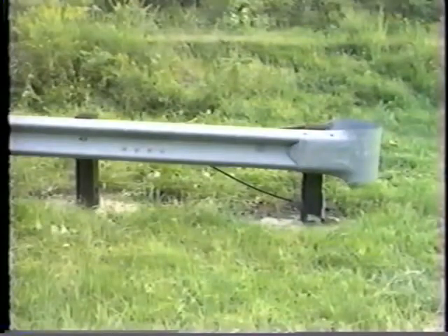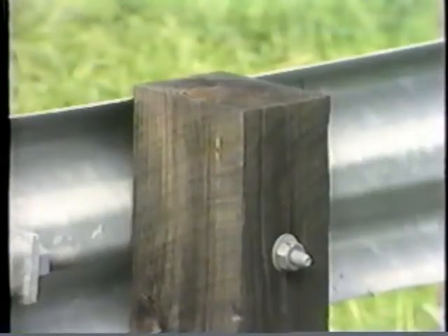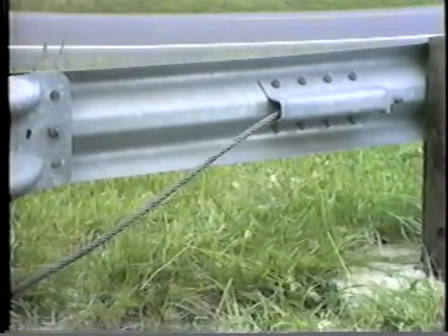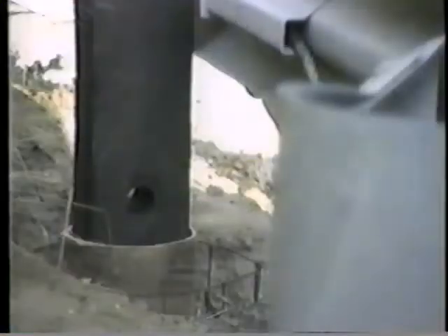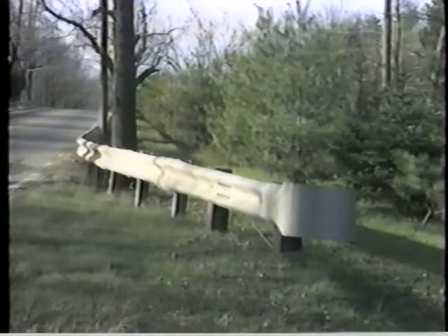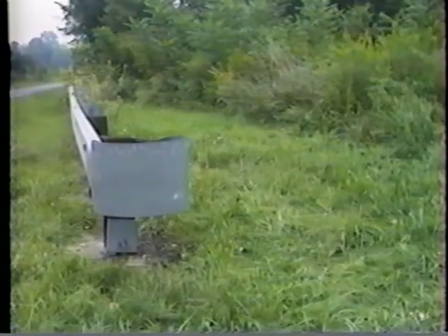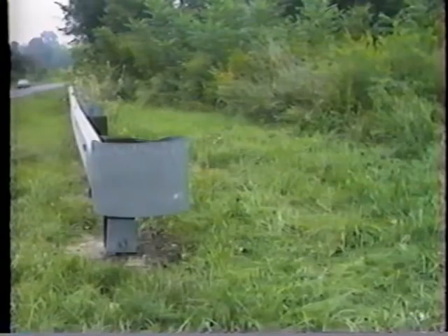There are 7 key elements that will normally determine whether or not the BCT will function as designed when impacted. These elements are post dimensions and the actual spacing of the posts, cable size, attachment, and tensioning, the breakaway system, either the hole in the wood post or the slip base on the steel post, footings of the first 2 posts of the system, the 4-foot parabolic flare in the last 37.5 feet of the rail, a critical element, the hardware used to connect the system, and available recovery space behind the end treatment itself.